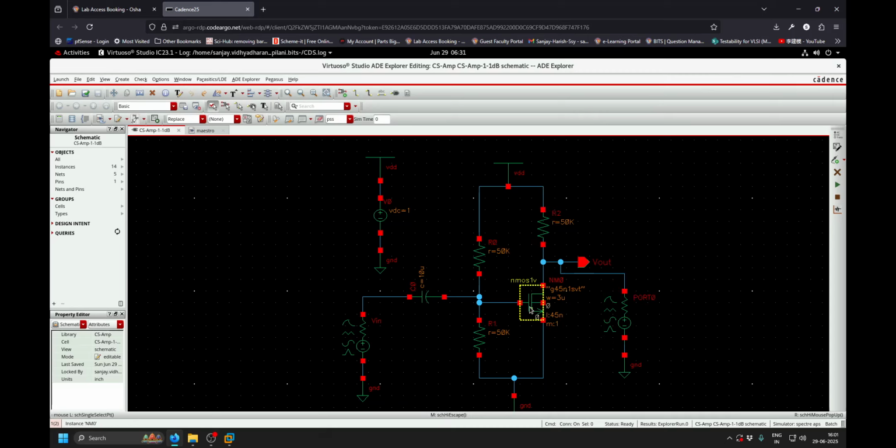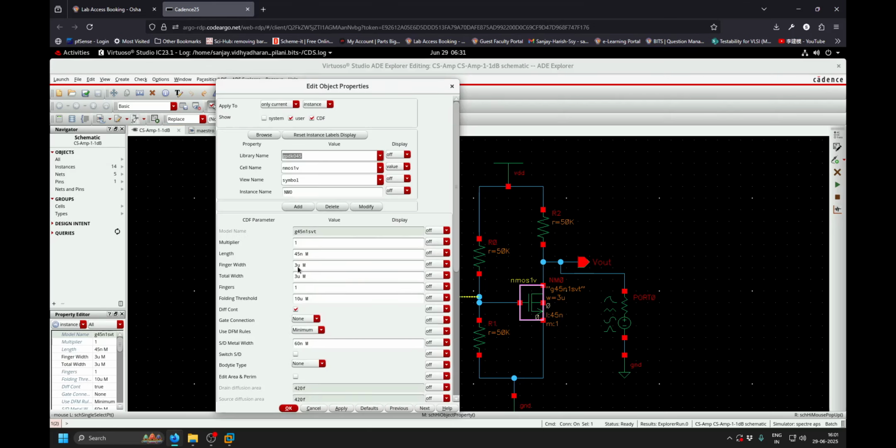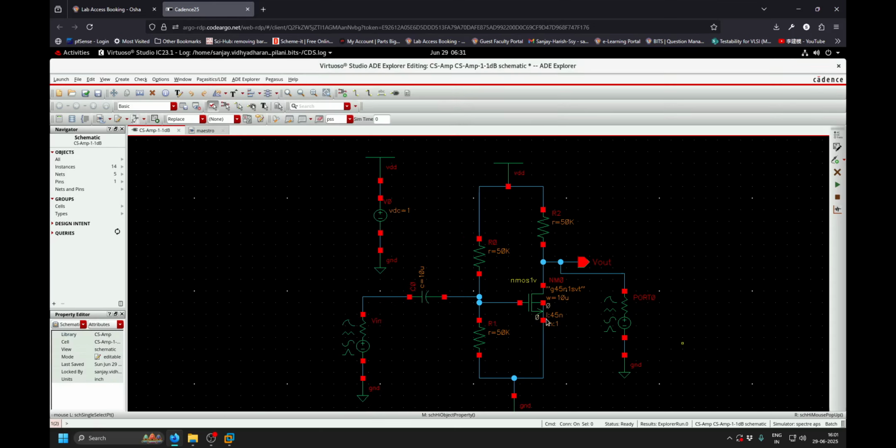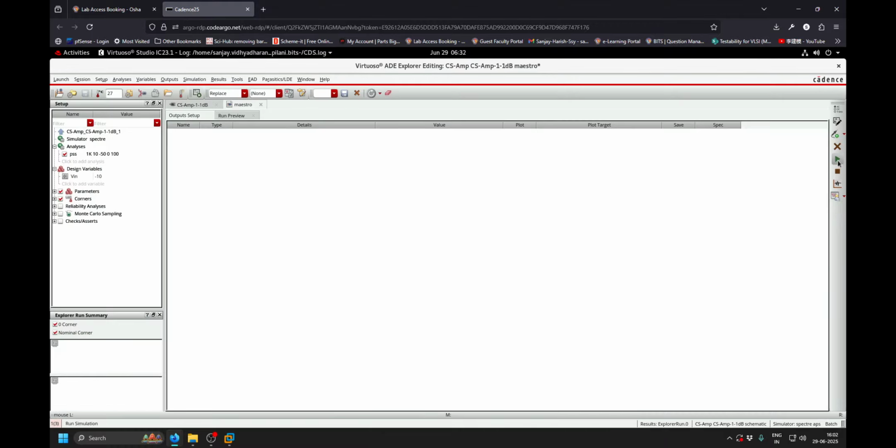Now I'm going to change this to 10 micro. So this is going to get my operating point close to 0. So the linearity will be adversely affected, and the compression point should come below -16. It is going to spoil my linearity because I have brought this operating point down. Initially it was at VDD by 2, and now I have pulled it below. So I run again out here.